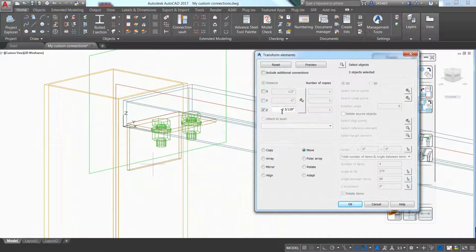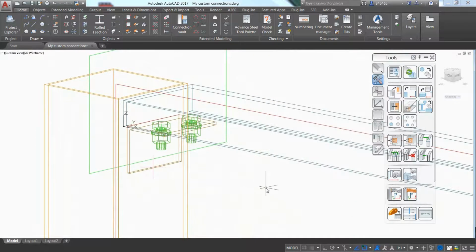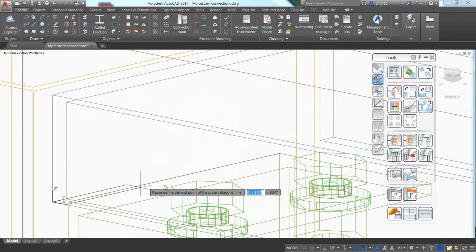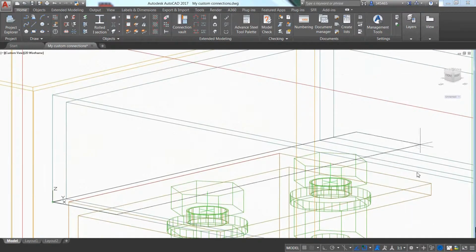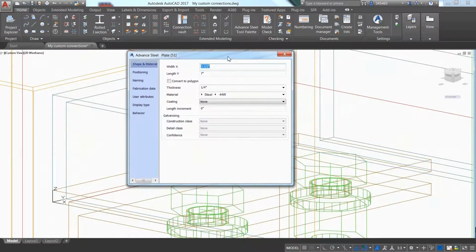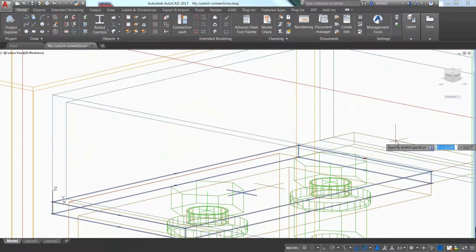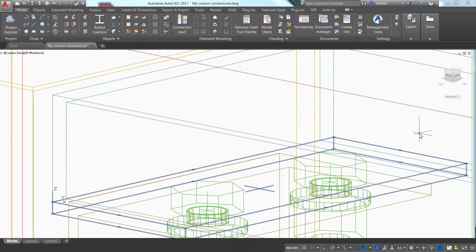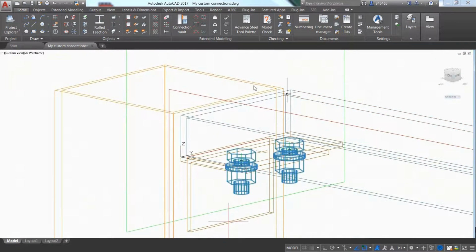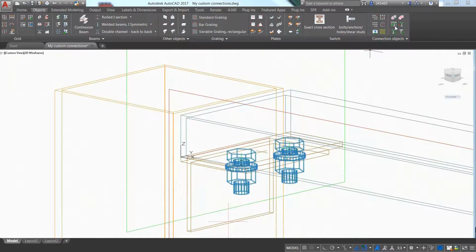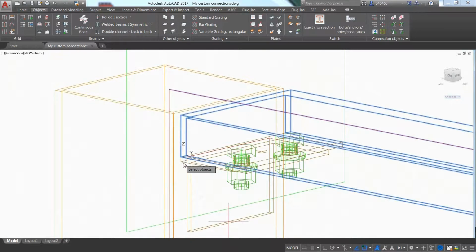It is easy to insert a plate in the current XY plane by picking two diagonal points, and its properties such as its thickness or side can be modified in the dialog box. If the plate size does not correspond to your expectations, you can stretch the plate by moving one of its grip points. You can use a dedicated tool to add an element to a bolt group, and the bolt length is then automatically recalculated. Advanced Steel allows you to connect parts using bolts or welds.